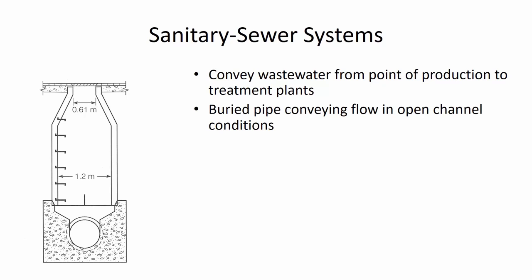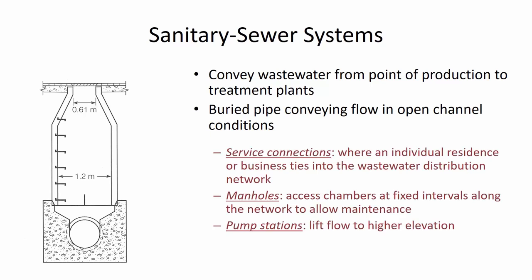You'll remember way back we did a comparison of the Darcy-Weisbach equation and the Hazen-Williams, and Manning didn't do so great in that head-to-head comparison because that was pressurized flow. But in this case it's not pressurized flow, it's flow that's flowing partly full.